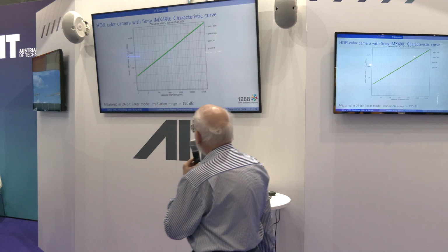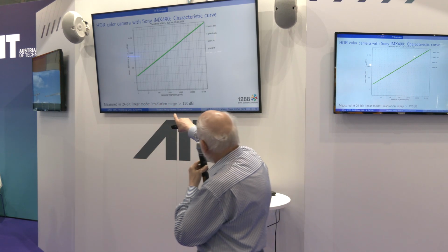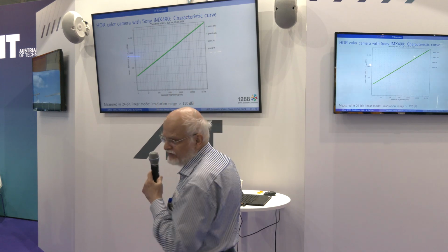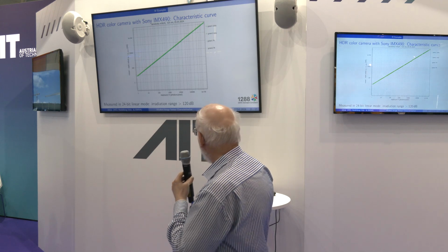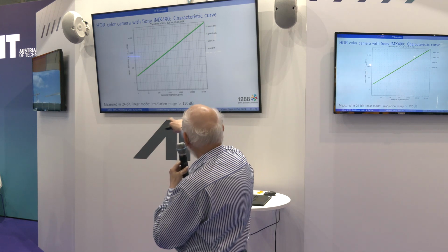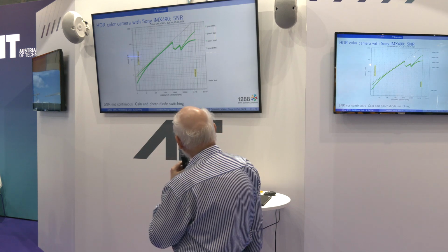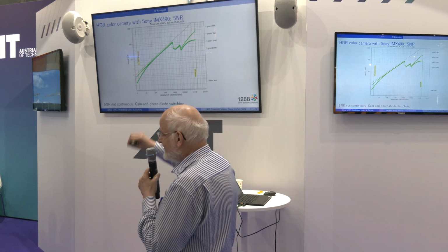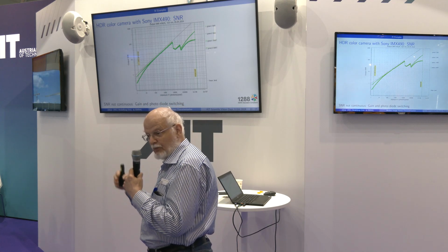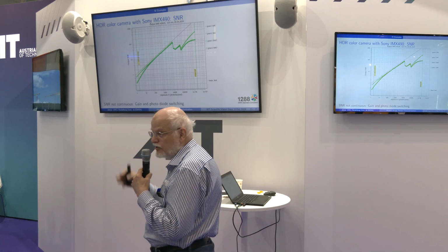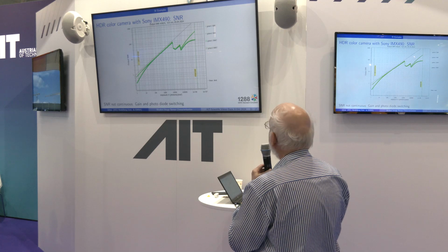Then we have a final example, the HDR color camera, which is measured here. You see all of it is linear behavior. It's a 24-bit signal, so 1 million, from 1 photon to more than 1 million photons. And the SNR looks, of course, different now, because there is switching between a large photodiode in the dark range and a small photodiode in the brighter range, and 2 different gains. So you actually see four parts in this curve.